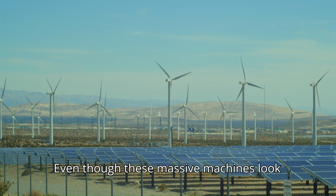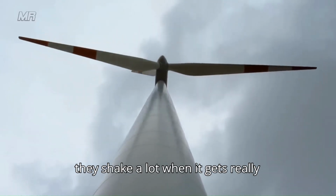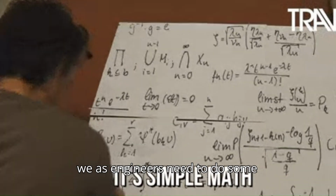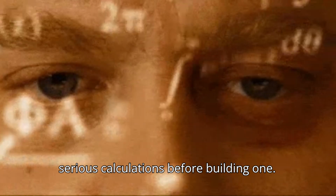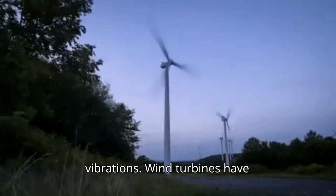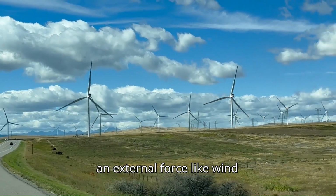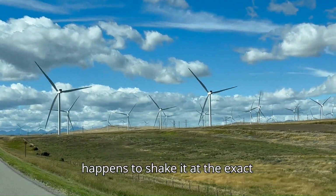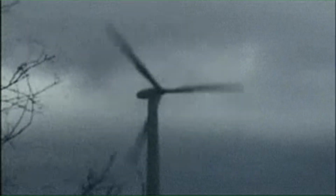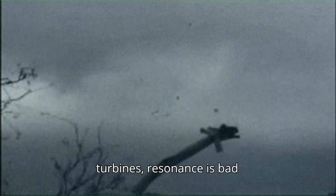Even though these massive machines look solid and unshakable, trust me, they shake a lot when it gets really windy. And that's why we, as engineers, need to do some serious calculations before building one. One of the key things we focus on is vibrations. Wind turbines have their own natural frequencies. If an external force like wind happens to shake it at the exact frequency, it can trigger resonance. And trust me, for huge structures like turbines, resonance is bad news.